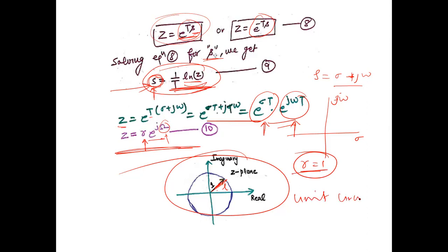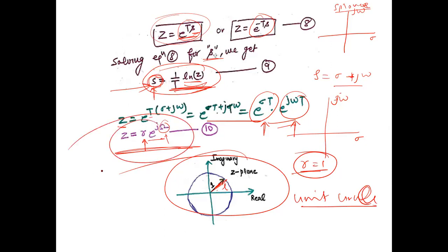circle. So this is the identification of the z plane, because in s plane what we have is the imaginary axis j omega and a real axis sigma. So this is what S plane is. But Z plane is not represented like this. Z plane is generally represented by a circle with radius r, right? So if r is equal to 1, we will call this circle a unit circle, and it plays a very important role in the analysis, stability analysis of discrete time systems, right?